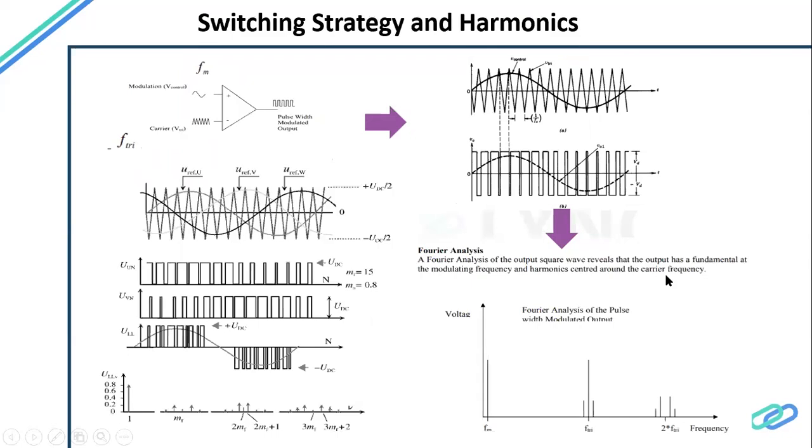And then we have to see what kind of harmonics we expect. Okay, so PWM is generated through a carrier and a sine wave. So what we are more keen on is what kind of frequency this has, because those frequencies will have harmonics around them. So we can see the harmonics are in multiples of this carrier frequency.